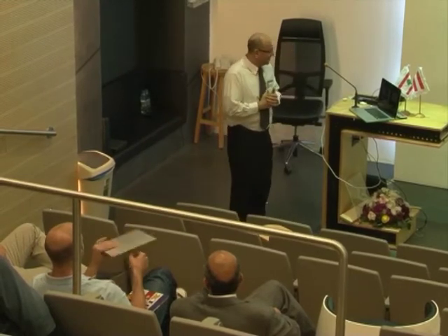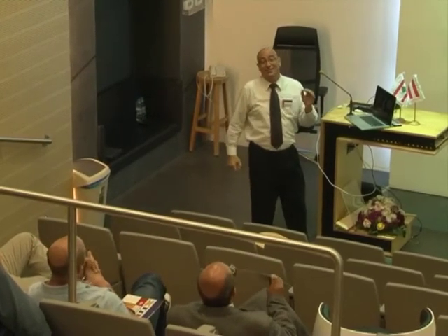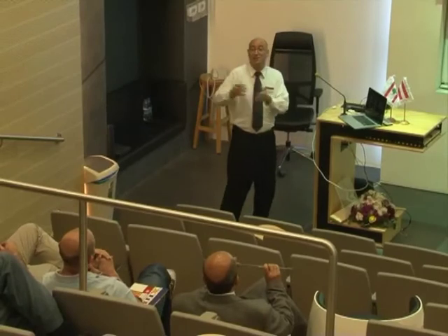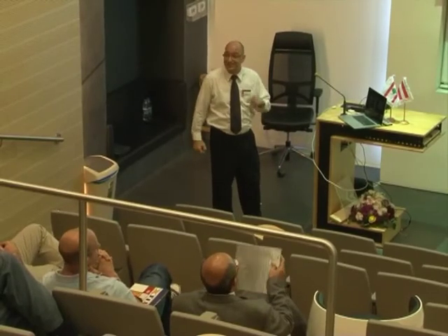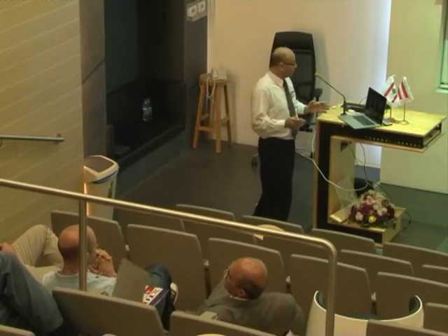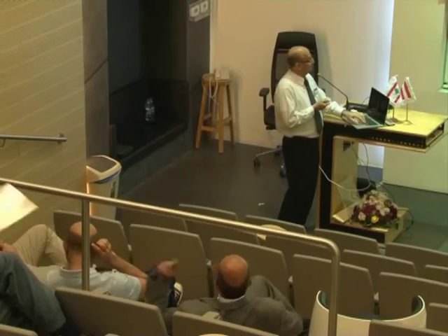Hardening. Hardening, exactly. Very good. Plus one. So basically it's for grain control, if you know what you're doing. Remember that this weld resulted in stronger material in the weld in a way because we have refined the grains in the weld area. So we take advantage of that fact and we do FSP.